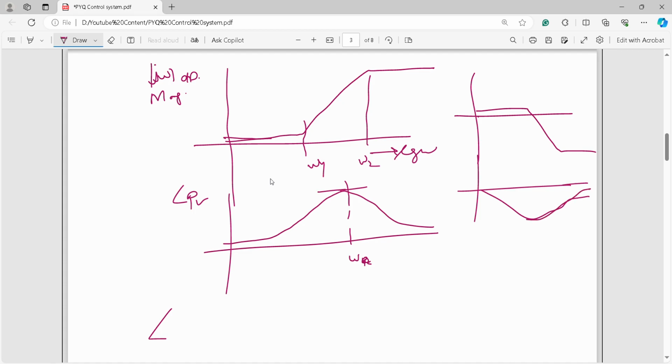But generally, for practical purposes, I'm telling you, the lead compensator, its name itself says we use it for providing phase lead. But the lag compensator, generally we are not using as a lag. We use it based on our requirement, for giving more gain in the lower frequency region, so that the system tracks better, is stable, and robust. Okay, we will discuss this in more detail in our coming lecture.